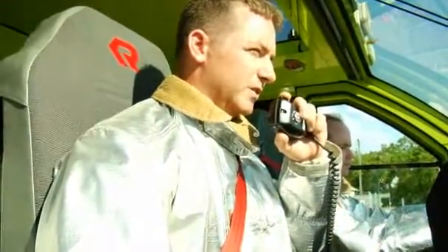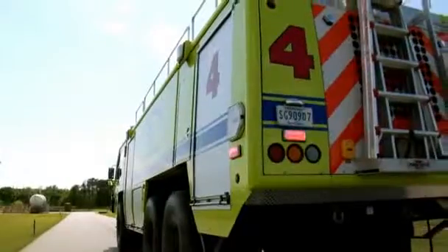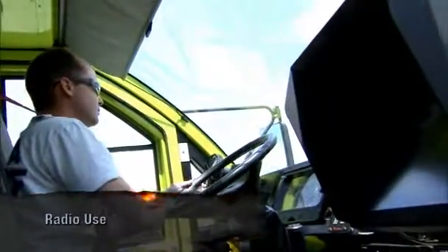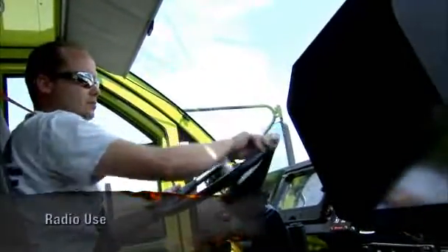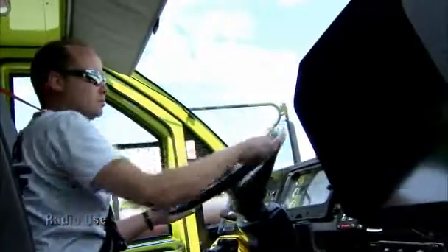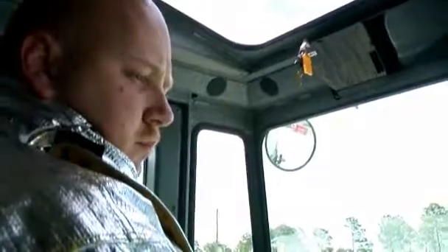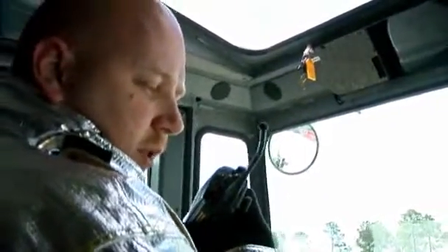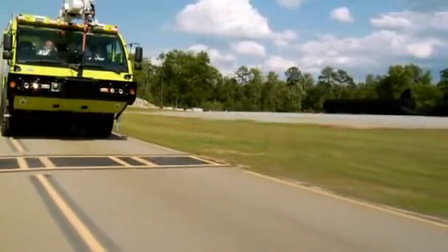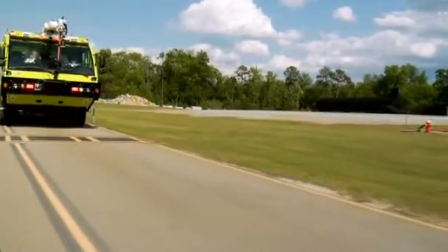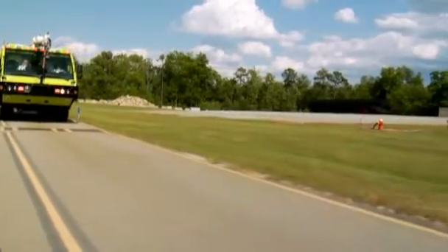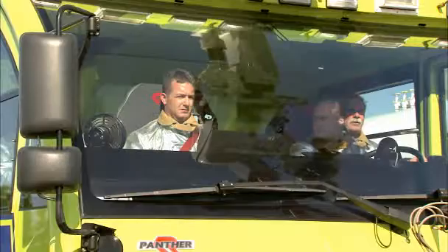Airport communications must be clear and concise. Standard protocols help minimize the risk of confusion or misdirection. The most important guideline is to listen. Listen to the ground and tower frequencies when moving around the airport. Listen before speaking to make sure no one else is transmitting at the same time. Overlapping transmissions are useless. If you don't understand a transmission, ask the sender to repeat it. Misinterpretations and mistakes can and will occur.